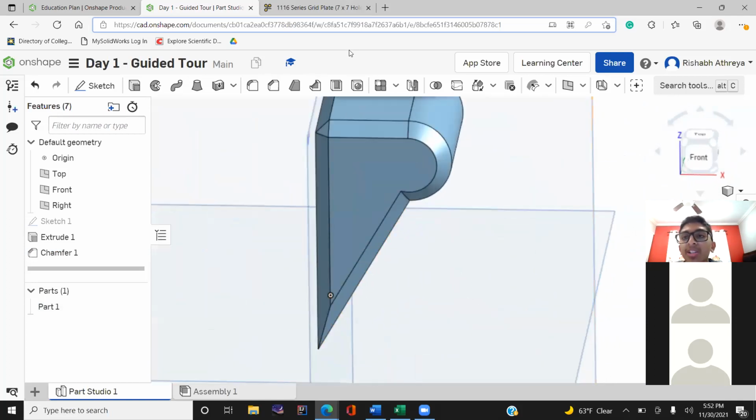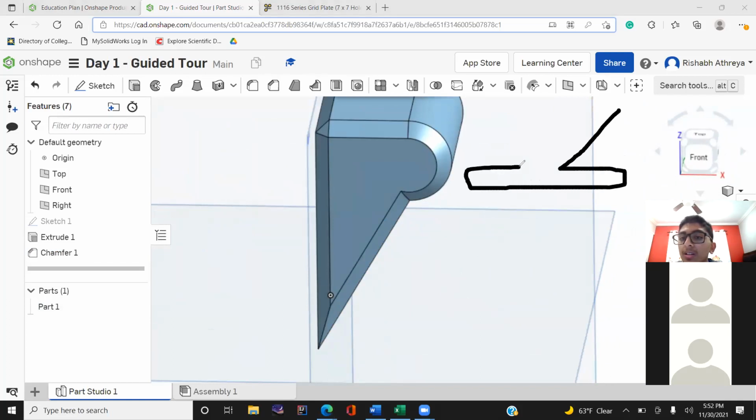If you have a shape that looks like this, a shape that looks like this in your mechanism, in your design, then you have a lot of load in this direction here. You don't have too much support right here, like you don't have a brace over here holding that up. It's prone to breaking at this point here. This part here can snap pretty easily.